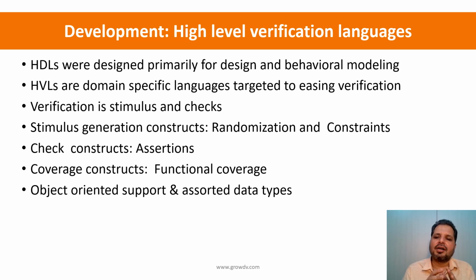So once you have modeled the waveform, now either you can use that waveform for checking certain functionality or covering that particular functionality, which is mostly applicable for the simulation world. But in formal, you can use that waveform that you have modeled to tell the formal tool to generate the possible variations of the waveform characteristics that you have captured. So that is how the assertions become useful.